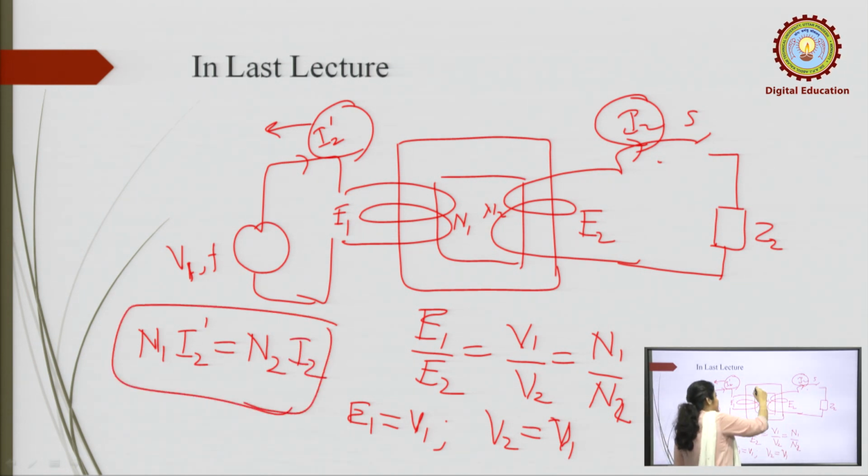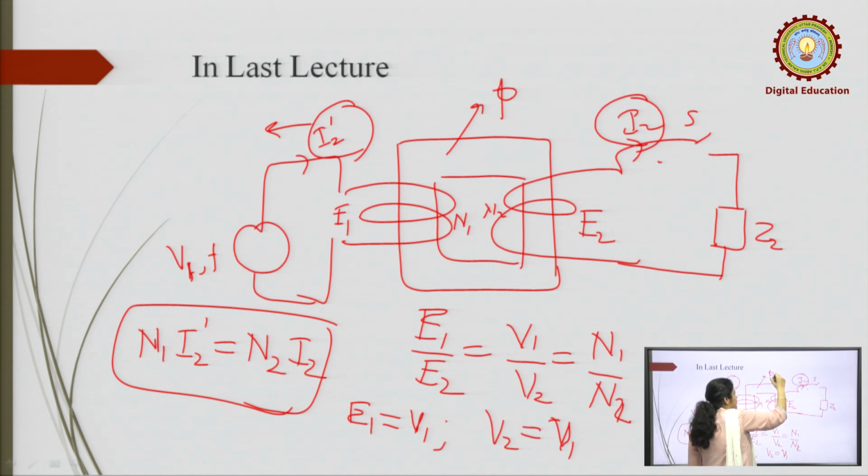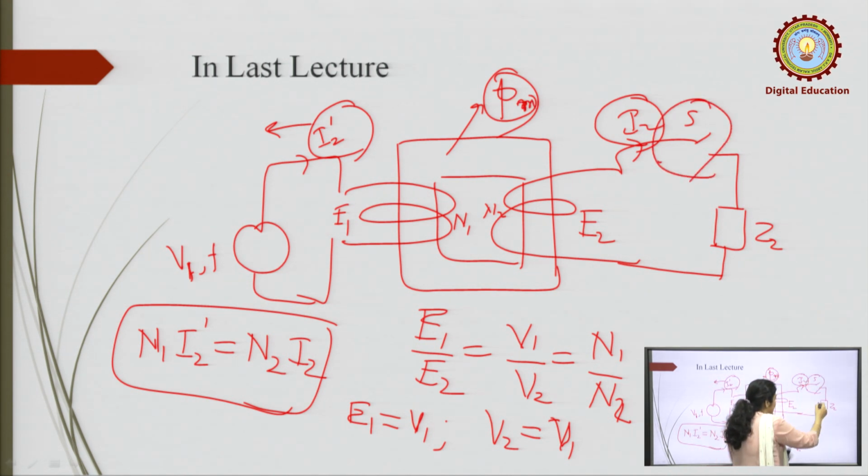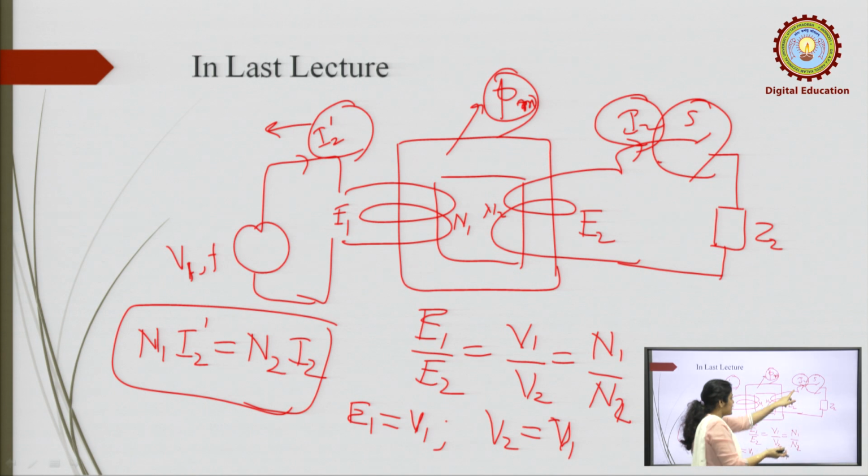In this case, the useful flux, or the magnetizing flux, remains constant whether the switch is on or off. As the loading effect takes place and the secondary current flows through the circuit, the same amount of current is drawn from the primary side so that it compensates the effect of I2 N2, and the core maintains constant flux.